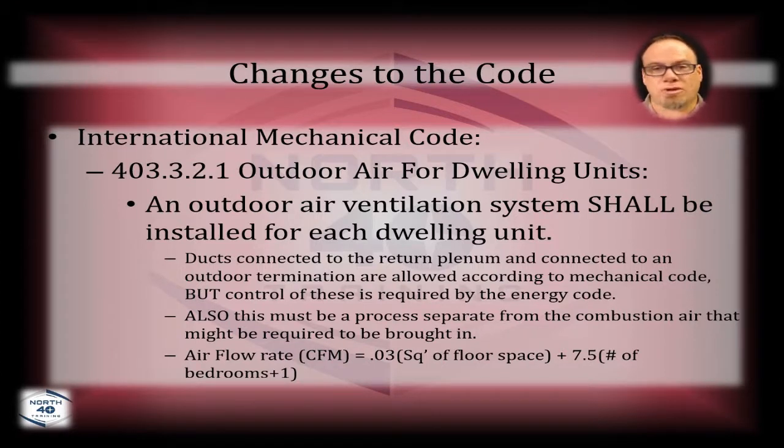That requirement for combustion air says if you've got a single pipe system or a natural draft system that draws air from the space that it sits in to burn, like a natural draft water heater, power vented water heater, single pipe 90% furnace, gravity feed boiler, any of those things that burn the air from the room that it sits in, you have to bring combustion air in from outside.